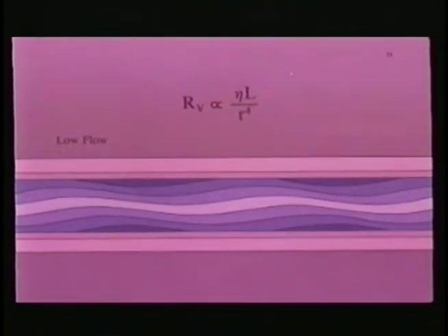31. A variety of factors affect the onset of turbulent flow and contribute to flow resistance during turbulent flow. The next few slides show the development of turbulent flow due to increasing flow velocity. Here, during streamlined flow through a tube with uniform diameter, the flow rate is low, and deviations in the paths of fluid elements from streamlines are so slight that only the viscous resistance factors affect the pressure-flow relation.